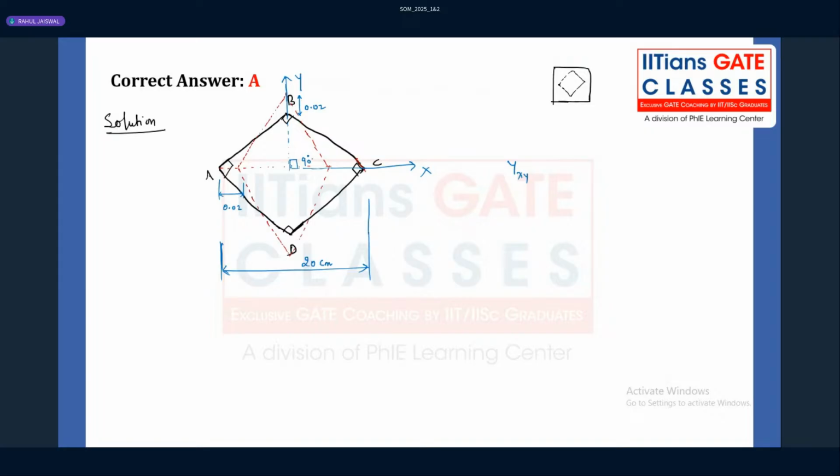The angle between these two given axes is 90 degree. And this angle between these two axes will not change even after deformation. Even after deformation, you can see the red color one, the x and y axes are still making an angle of 90 degree. So shear strain for the given coordinate system will be straight away 0.